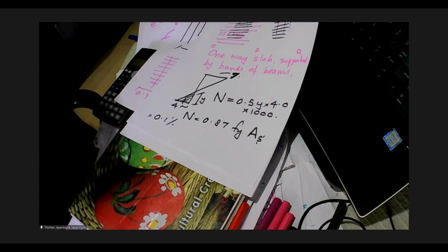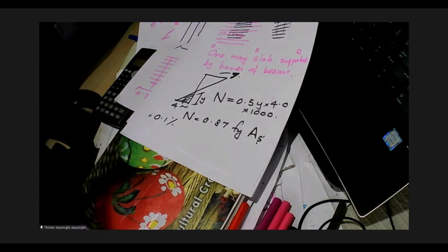The whole idea is we are compensating for the self-weight of the slab by using PT, and then we apply the loads and see. If the loads are very light, there is a perfect system, because once you suppress the dead weight, the slab will become an axially loaded panel, no cracks, so the deflections will be small.